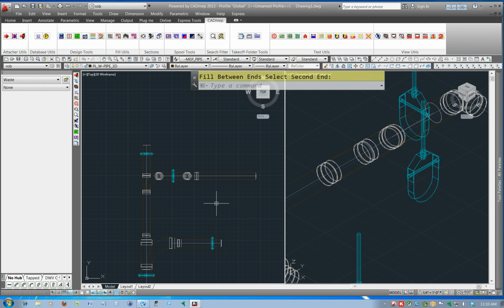Pitch pipe. Is that why you guys got this for doing plumbing work? Yeah, basically. Pitch pipe is the biggest pain in the ass ever. When you're doing water, you draw with your design line, and you're pretty much done when you're done with your design line. And if you need to change it later, it's no problem. With anything that's flat, no problem. But pipe pitch is always a pain in the ass.